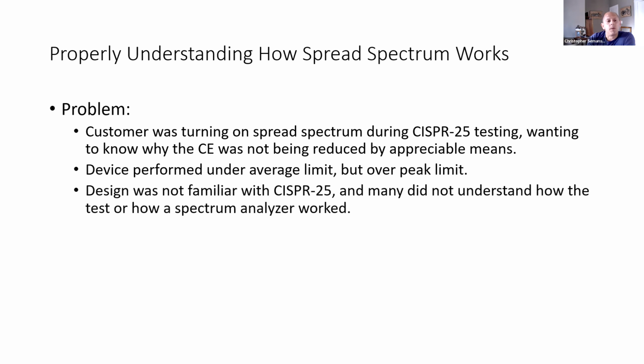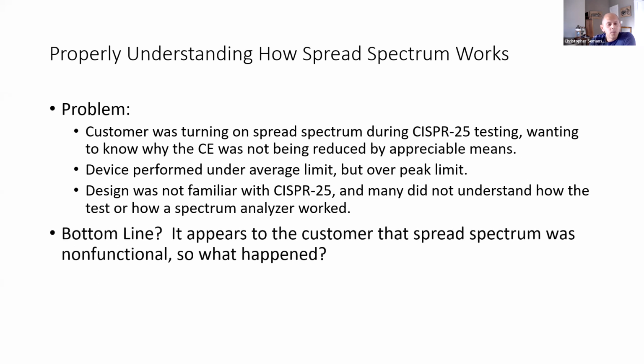So after talking with people, it was interesting. The individuals down here are not quite like Detroit. These guys are designers. They are really good at designing circuits, but when it comes to a system level thing, it's a little rough. They weren't familiar with CISPR 25, and many, including the other application engineer, not me, didn't really understand how a spectrum analyzer worked on the inside. And so the bottom line was that it appeared to the customer that the spread spectrum was not functional.